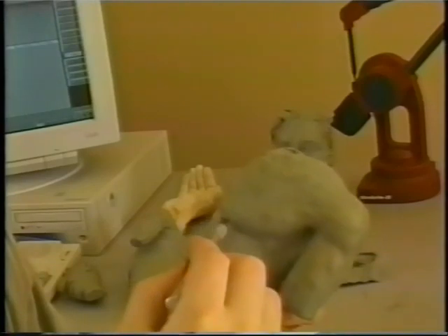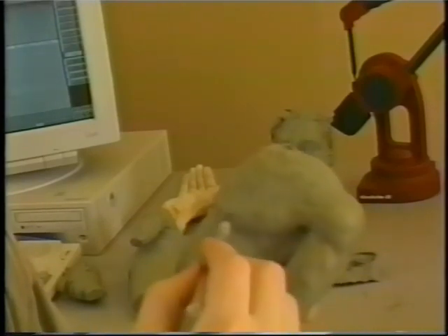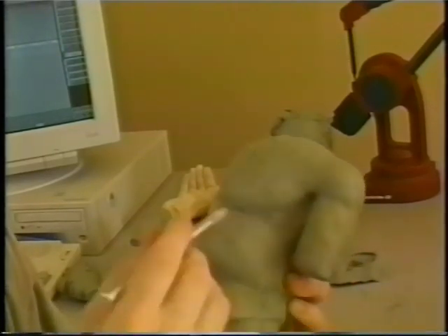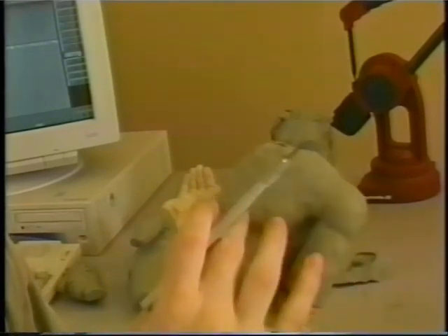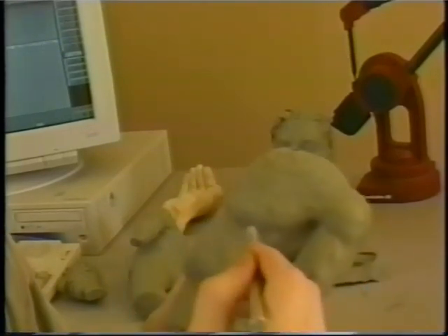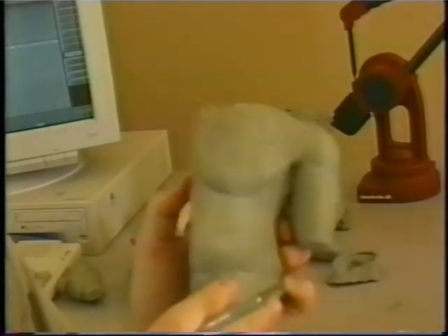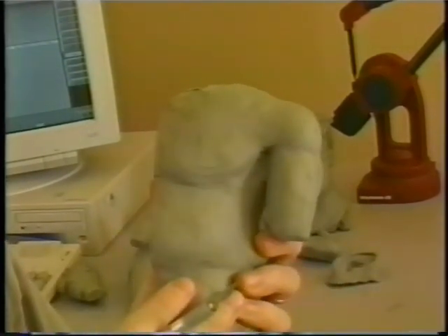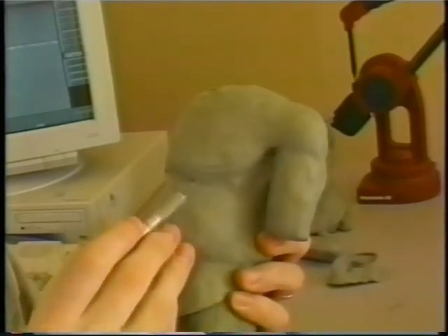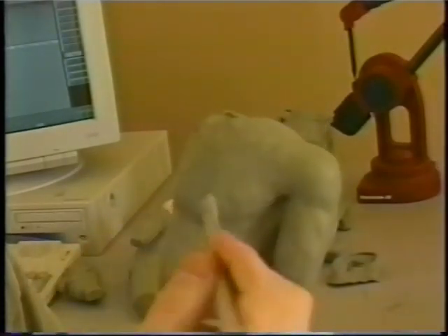So maybe something like that. And then rather than waiting till you're way up here on the surface, start maybe down here, then have another one right there. So wherever you have an area where you're going to want some extra detail, you need to double up your lines, and that way you can get that detail.